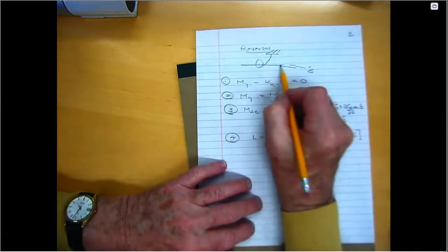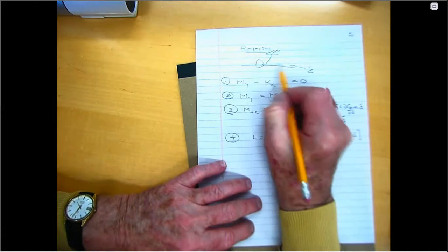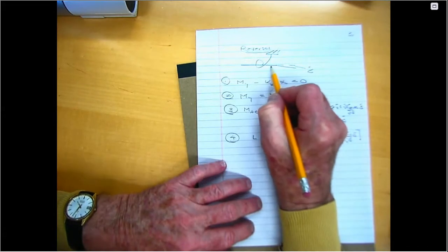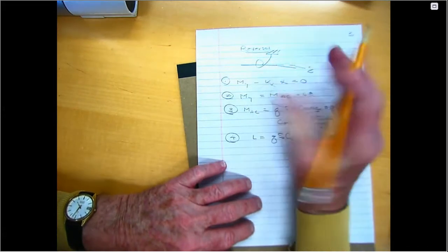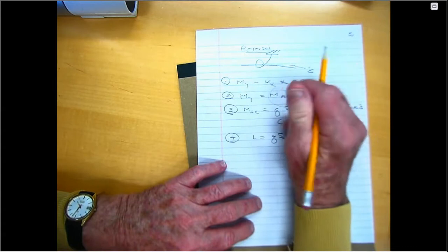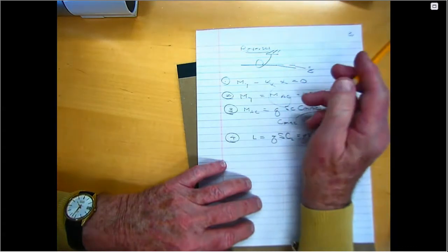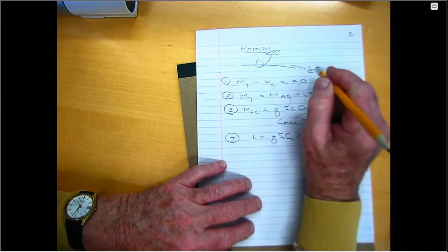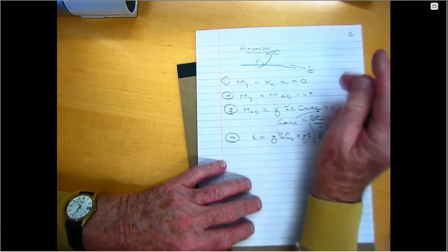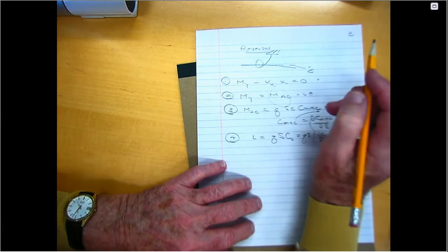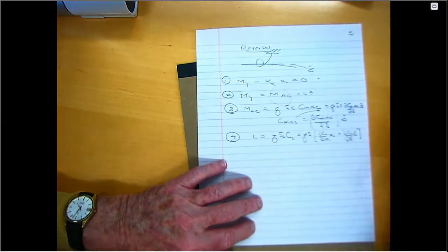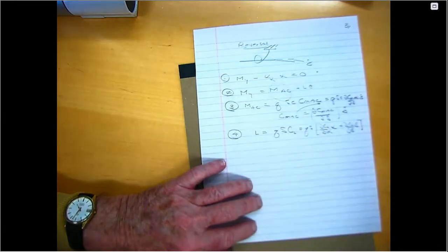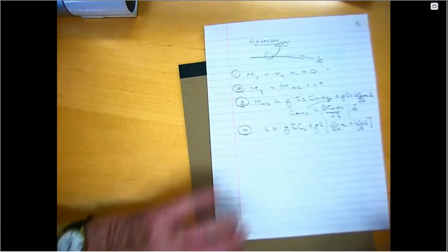In a more elaborate model, I would put another spring between the control surface and the main airfoil surface to represent the stiffness of that connection. It turns out, within the framework of linear theory, that the reversal condition doesn't depend on that spring, but that is probably not obvious to you at the moment. I just throw that in as an extra cool tidbit.